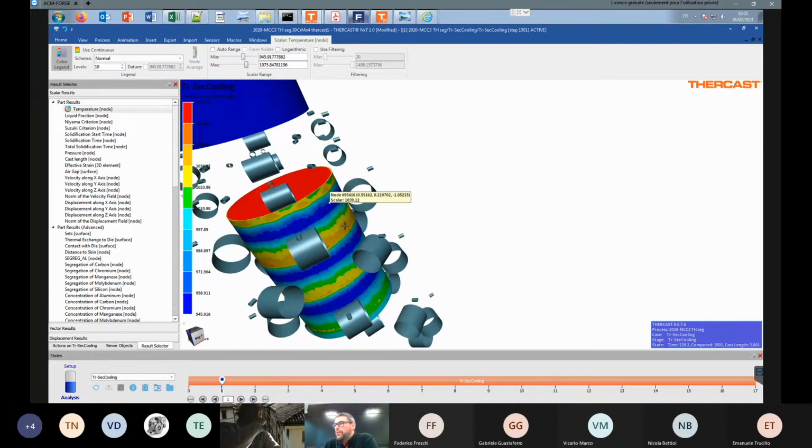Here it's a casting of a 600 millimeter bloom, and we are able to compare with real in situ measurements that are done with a pyrometer, for example, on the production site, and we are able to check the values and validate the numerical simulation in terms of evolution of the temperature on the surface, and so we are able to be more confident in the numerical simulation